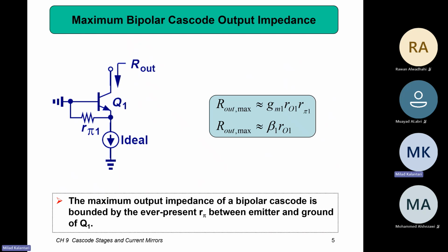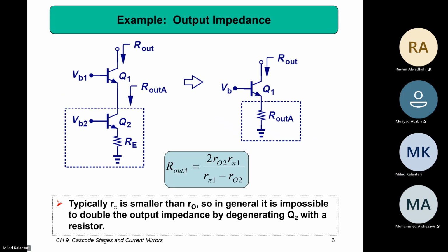So here it is trying to say that, in fact, if we could have this ideal current source, so here we had this transistor here. The transistor is acting like a current source at the bottom. If we could have the ideal case, then the maximum R out was this value, which we were simplifying, right?